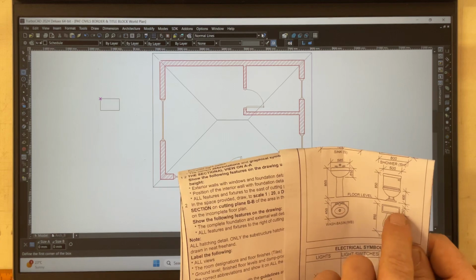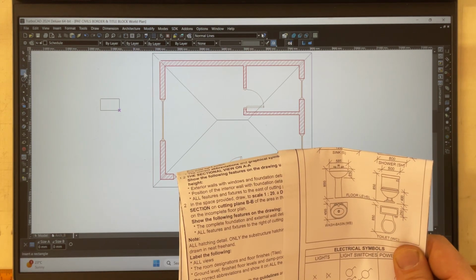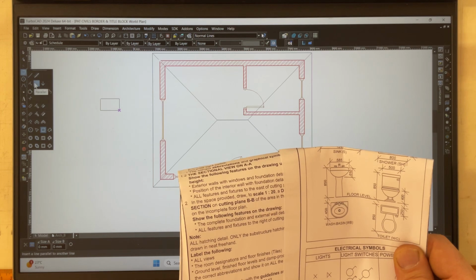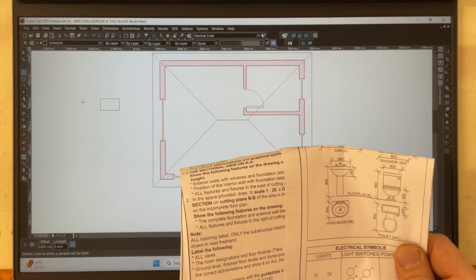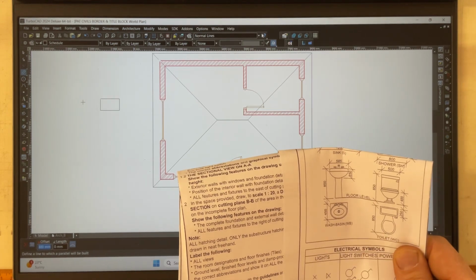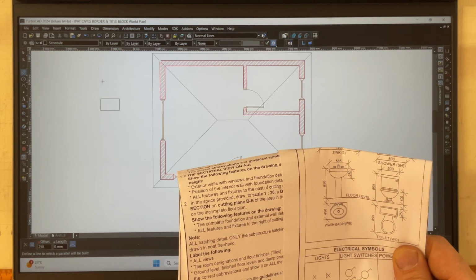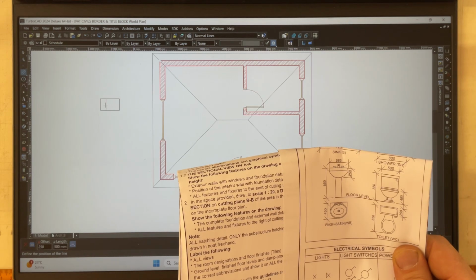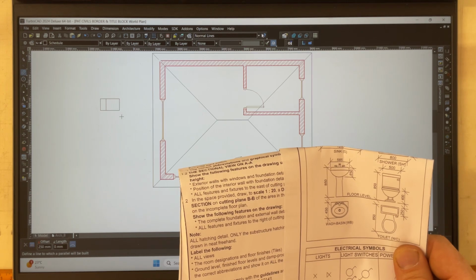It then tells me that the cistern at the back is 250 millimeters. I'm going to go into this thing over here, go to where it says parallel line. I then set the offset over here down at the bottom to that 250, press enter, and I now click on this little line over here. And there we go, I now have that 250 millimeter gap.